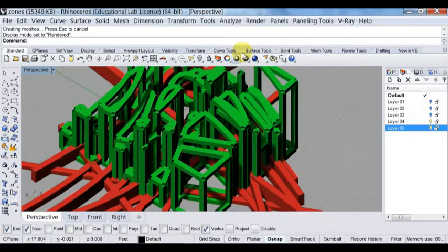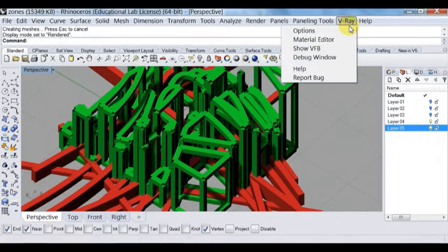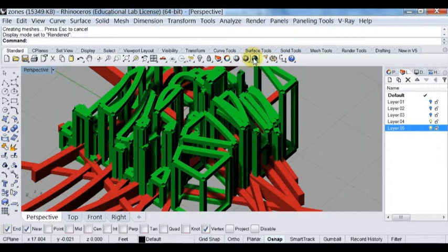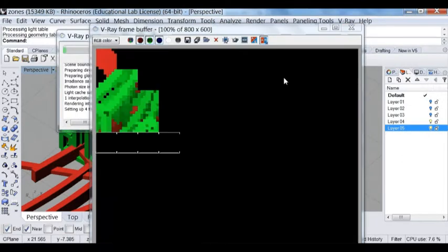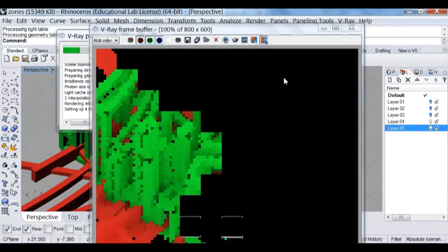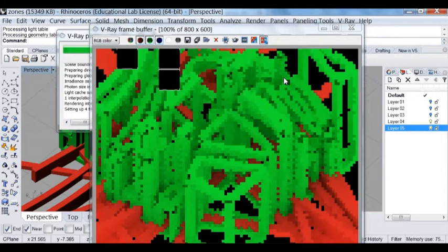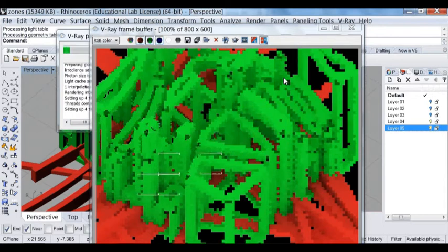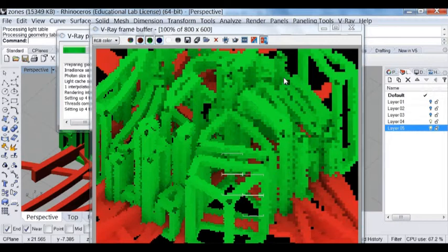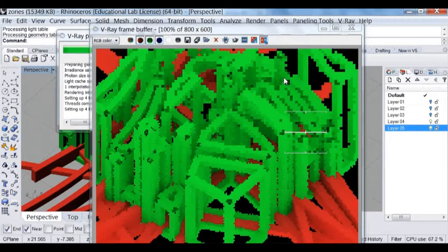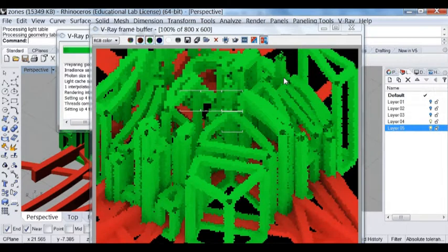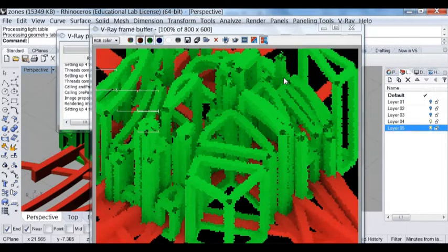Then I can go ahead and start to render. I think I still have Visual Render as the default engine, which will give you this kind of pretty nice soft ambient lighting. So here we go, we got the renderings. So use color as a way to define the zones. So green is one, red is another one. Okay, so this is the whole process. Yep, I think I will stop the video right here.